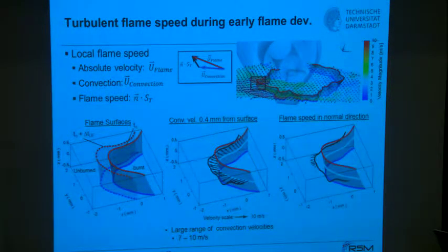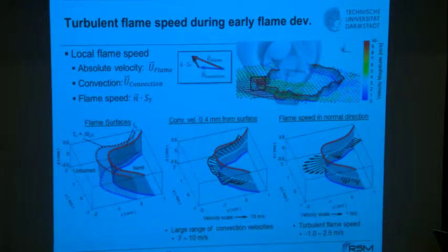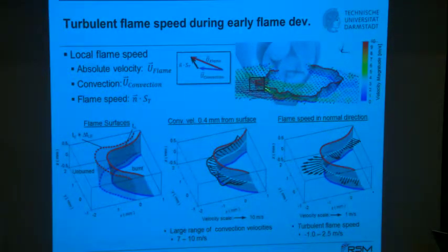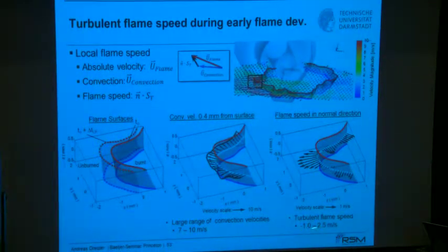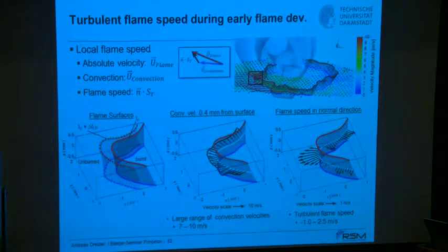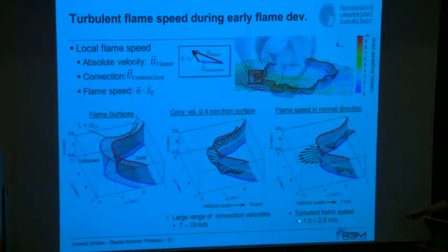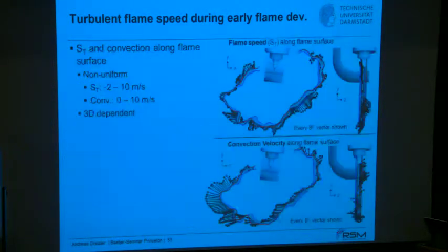And then the rest is the same idea, the same data post-processing to achieve then here the turbulent flame speed, which is for this realization in this small fragment here, in this small volume element, shown here to vary again in a certain range, including as well negative displacement speeds. Interesting is as well to visualize how the orientation is.